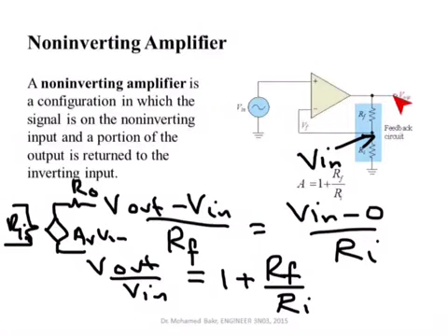So this means that if you apply a current source at this side, and this is how we do it for a circuit like this one, we apply a current source, and this current source we call IX here. Then this current source will see a 0 voltage across it, because the current here will all sink into the op-amp. There is no current flowing in these two branches. There is no current flowing here, and the voltage here is 0. So it looks as if this current source is really flowing into a 0 resistance. So the equivalent output resistance seen from this side is 0.